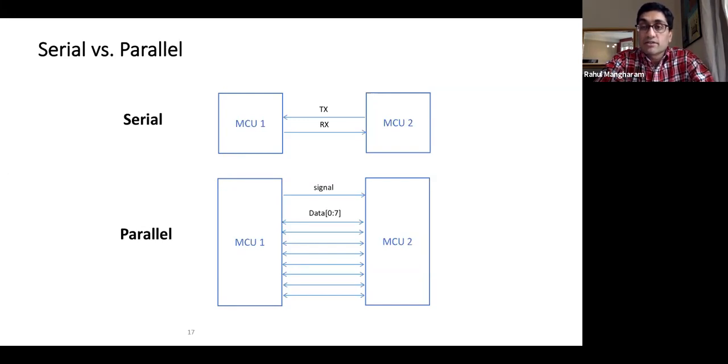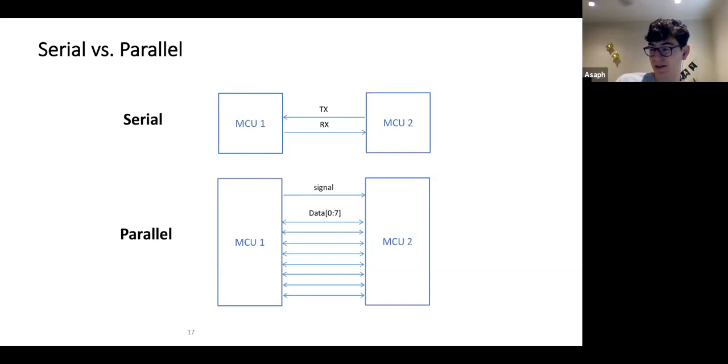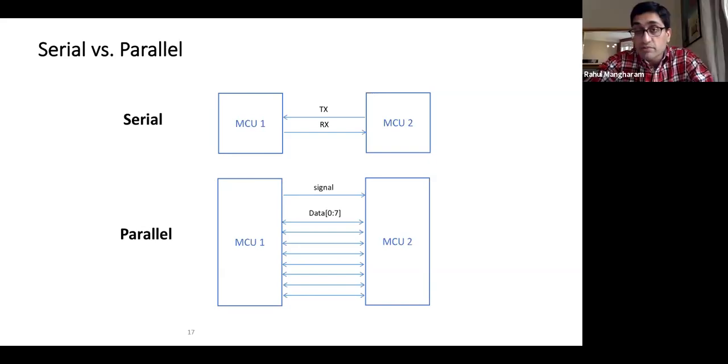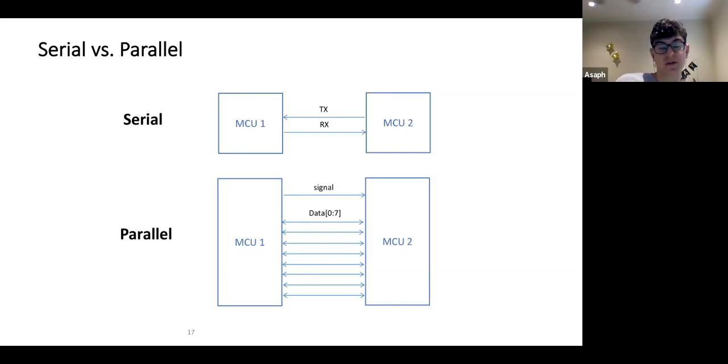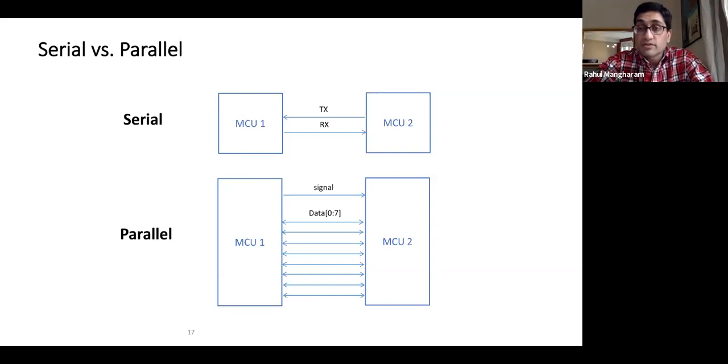Why is the whole digital industry trying to get to smaller and smaller chips, to fit many more transistors in the same size chips? Power, more energy efficient. But more transistors mean more power. But I guess if they're smaller, they consume less power. If they are smaller, they use less power, but they also have more leakage. That means they are also leaking power a lot more. So the answer is yes and no for power.